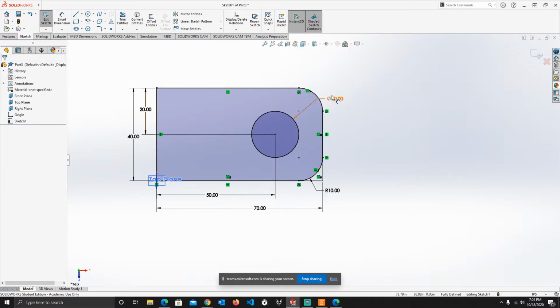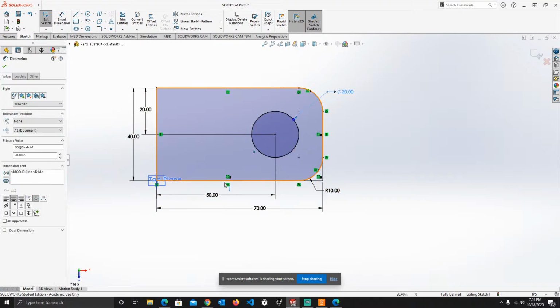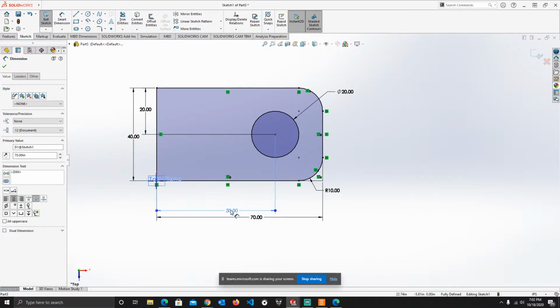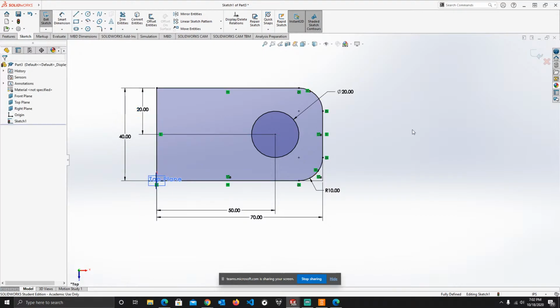So another thing now in engineering, usually you want to keep your dimensions properly arranged. So usually the biggest dimension goes all the way out, and as you keep on getting closer, you arrange them like this, right? That's just so that when you make a graph, a sheet, then it will be properly arranged. So anyway, that's our circle and that's our object that we made.